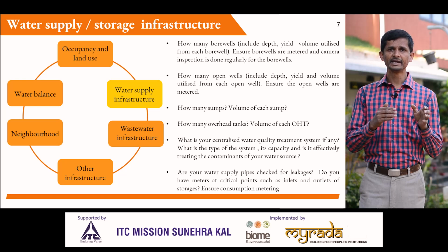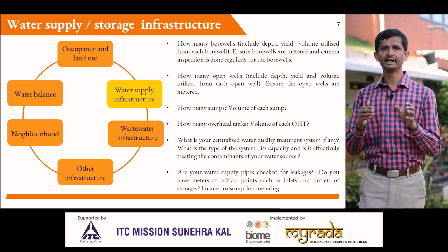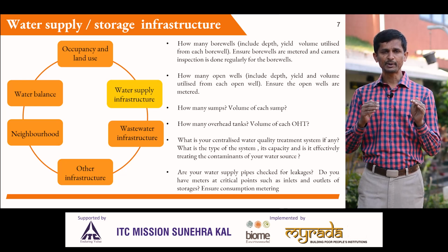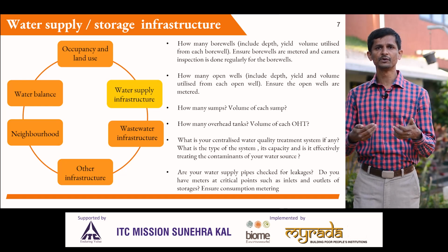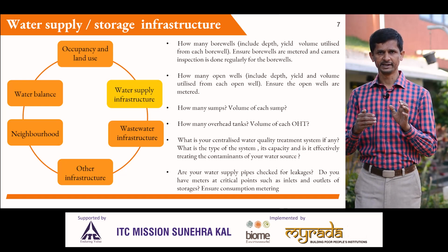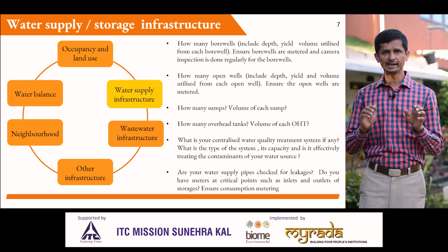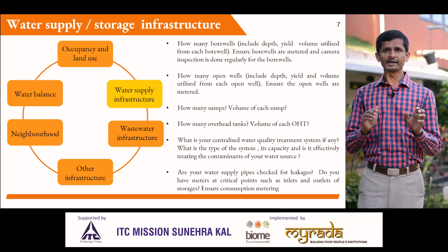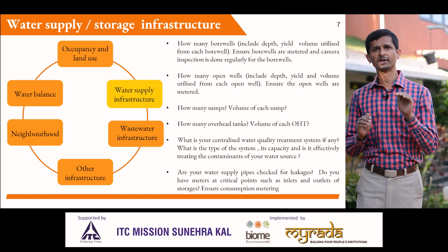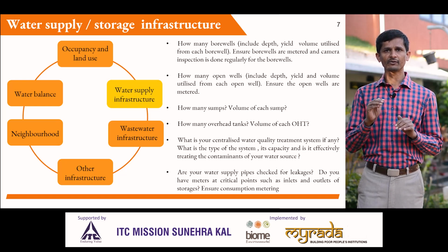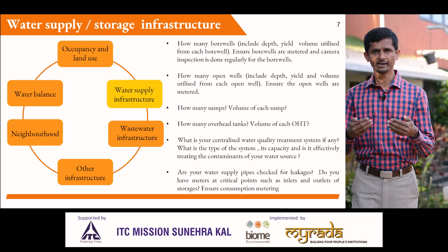Also identify if any leakages are there in the storage structure and supply pipes, which is essential to know what the real consumption is. Ensure your water treatment system is not an overkill and water quality is monitored regularly at the source level too, in addition to the water quality treatment before supply.